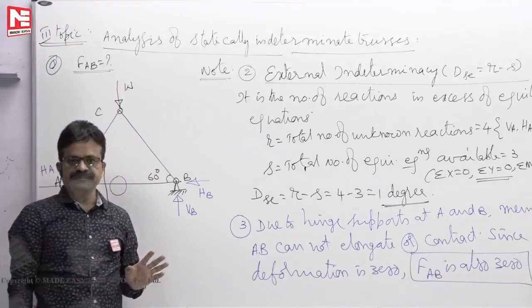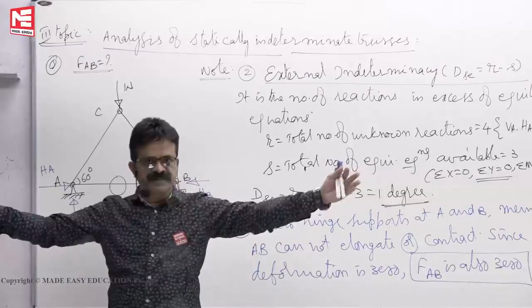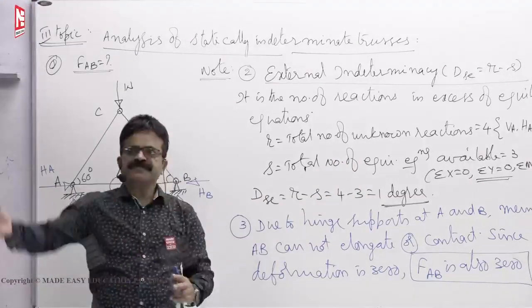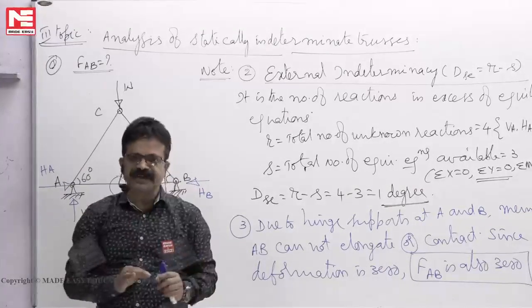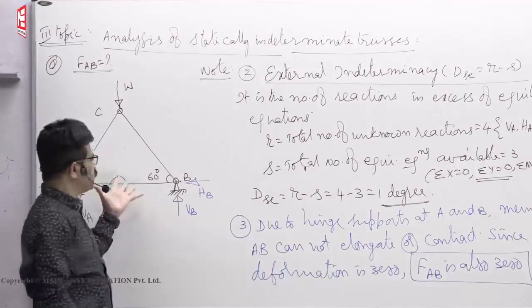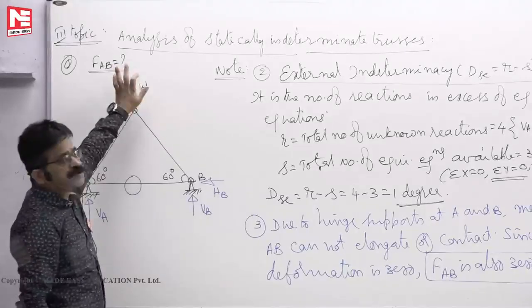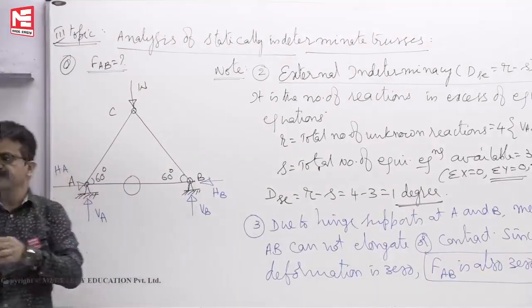be loaded. This is again the same situation here. From outside the wall, whatever amount of force you apply, it will not be loaded. If someone comes through the door and they apply some temperature, then it will be heated. Same situation here also. Due to temperature changes, there will be forces in the member AB. Otherwise, due to applied load, it cannot be stressed. Okay.